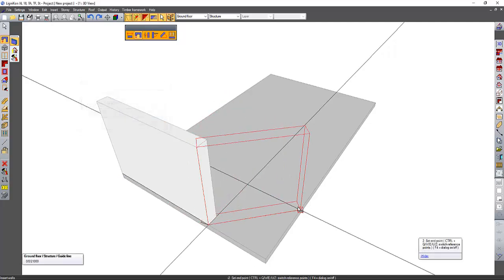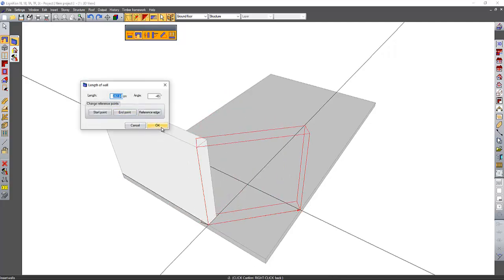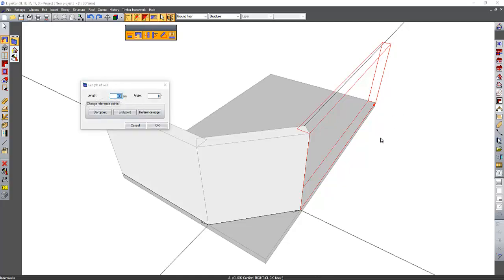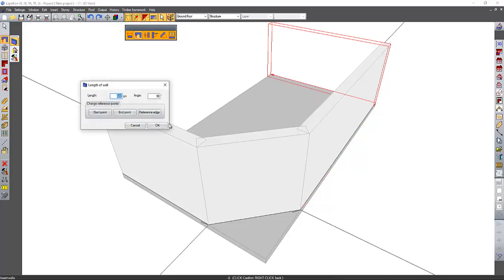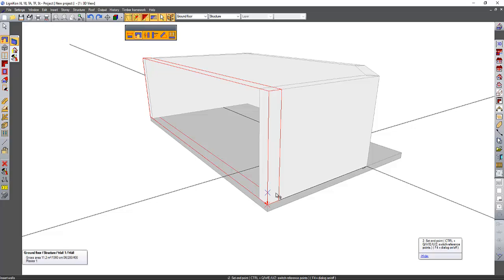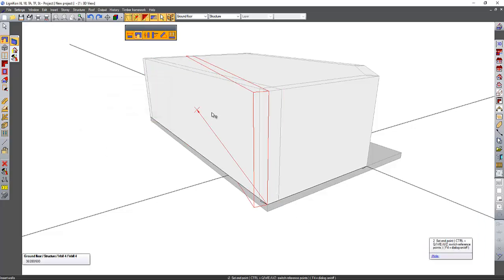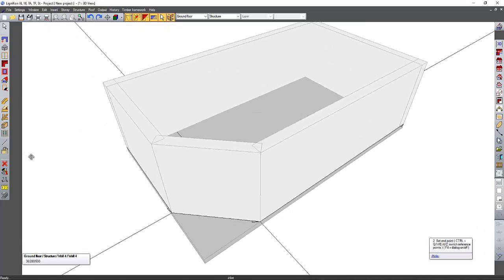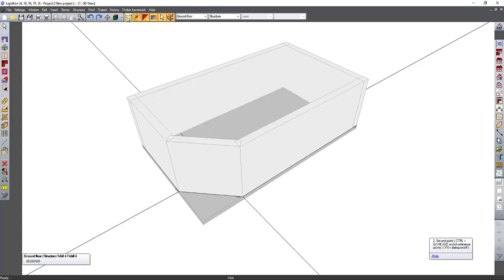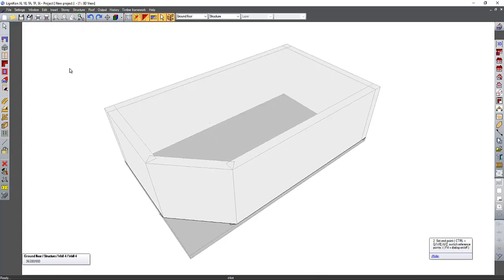So my wall is defined automatically following the clicks that I'm making. You see, this is the length, and this is the degrees that you can change if you want the angle. So I confirm it, or you just click the corner point where there is the snap and everything will be fine. Okay, I hide the guideline, we don't need it.